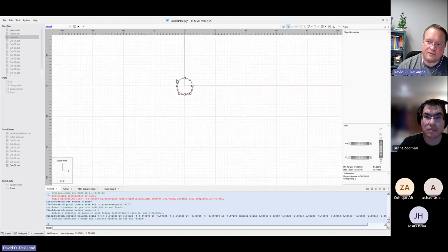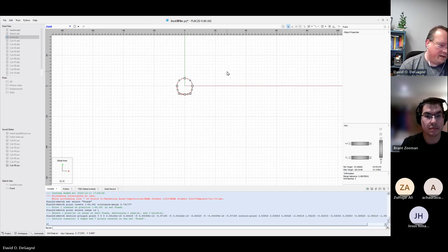And then sometimes there are little tricks that we need to play. If you wanted to have very fine zones around the tunnel, you might put a box around that, specify you want 1 meter zones or half a meter zone length, and then have another box around that that's specified to be twice as big.